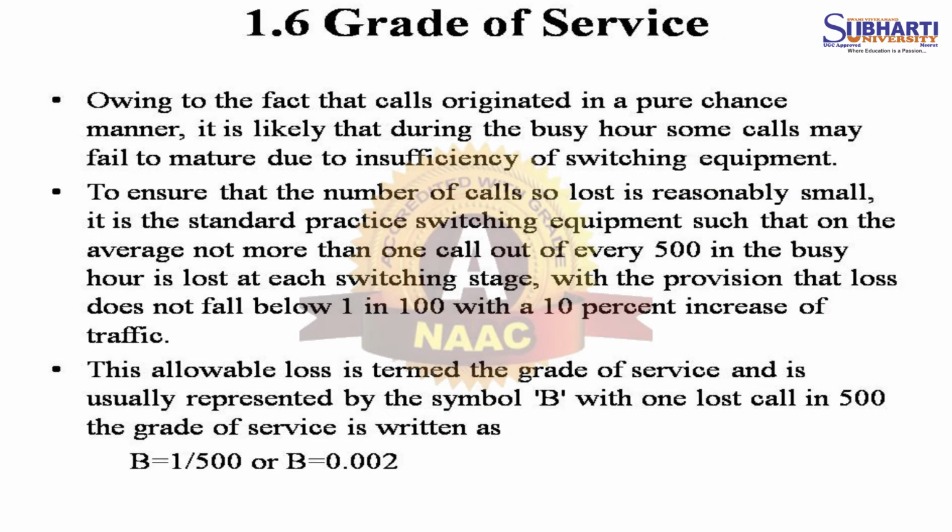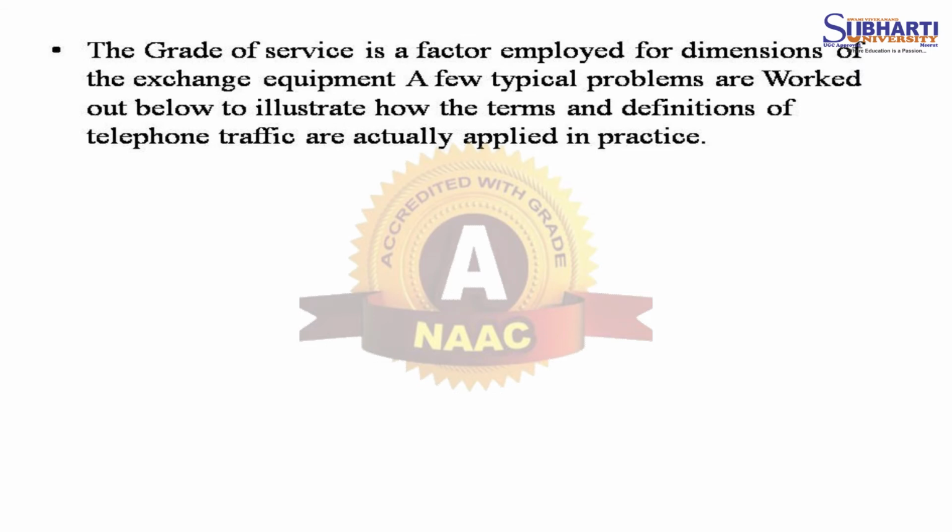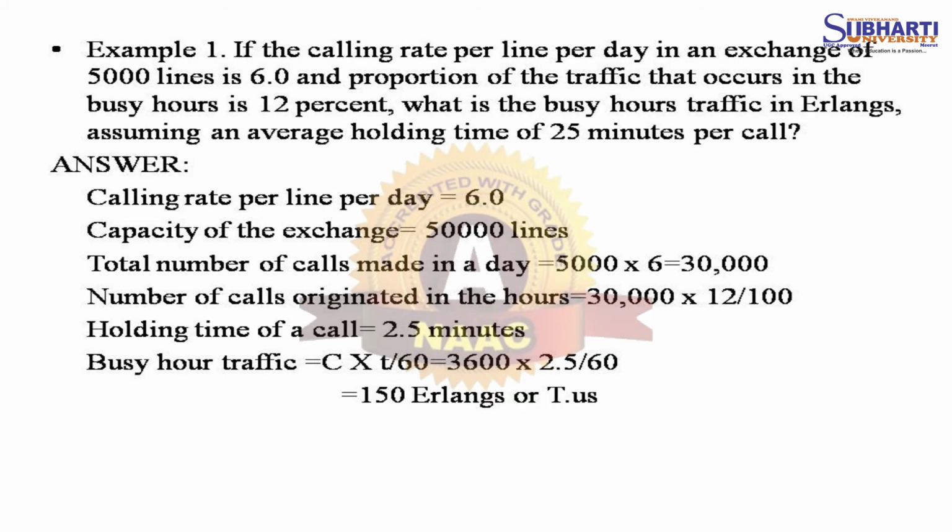Grade of service. Owing to the fact that calls originate in a purely chance manner, it is likely that during the busy hour some calls may fail to mature due to insufficient switching equipment. To ensure that the number of calls so lost is reasonably small, it is standard practice to provide switching equipment such that on the average not more than one call out of every 500 in the busy hour is lost at each switching stage.